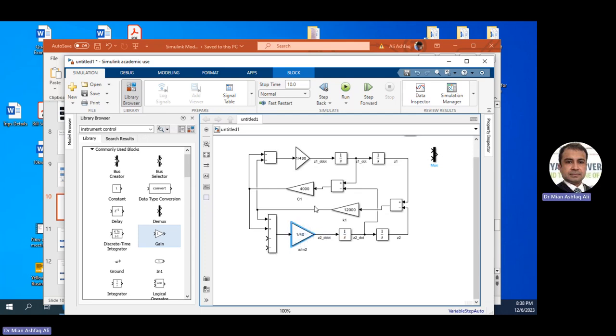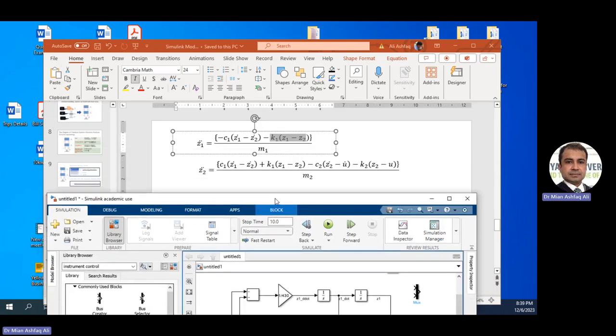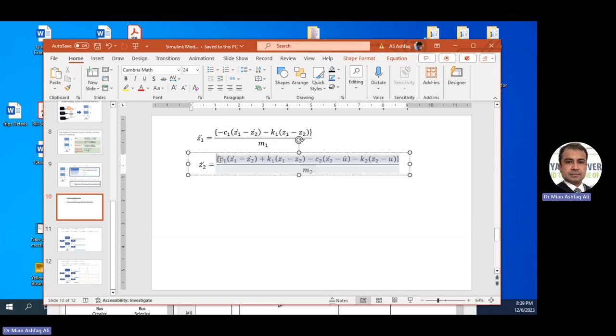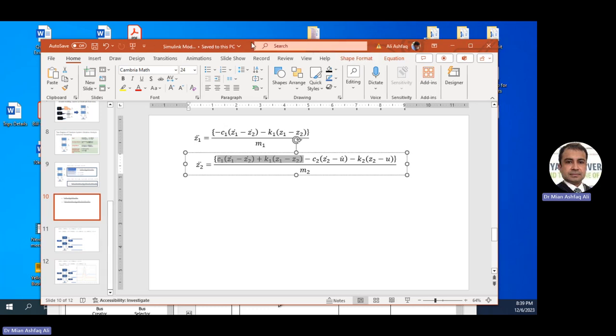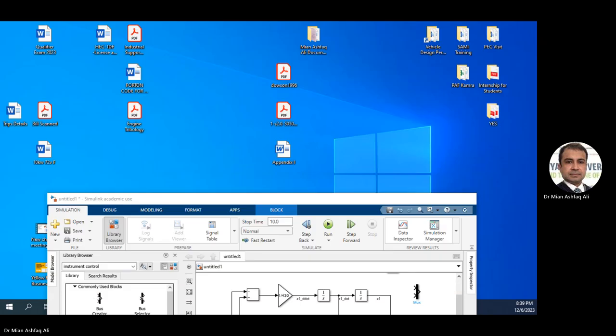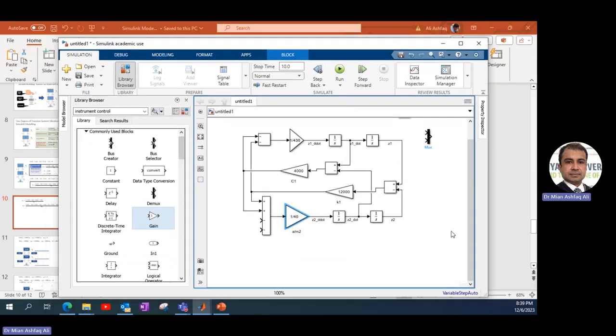And then those two signals are actually what? So we can see from here, for Z2 dot, we have dealt with the first two, this term and this term. They are already done because they were readily available from the previous equation. We also need to know how to evaluate this one. So C2 should be negative, and it's the difference between the road velocity and the input velocity. This means that I can simply have a road profile parameter.